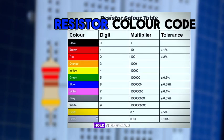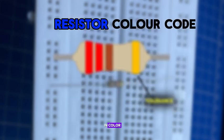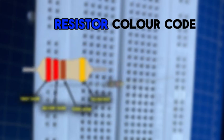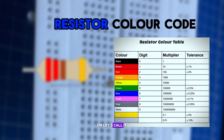To read them, hold the resistor such that the tolerance band is on your right. The tolerance band is usually gold or silver in color and is placed a little further away from the other bands. Starting from your left, note down all the colors of the bands and write them down in sequence. Now, use the table given to see which digits they represent. The band just next to the tolerance band is the multiplier band. So if the color of this band is red, representing 2, the value given is 10 raised to the power of 2, or let's call it 0, 0.